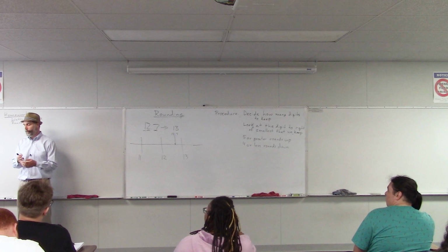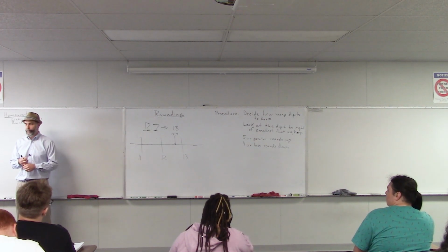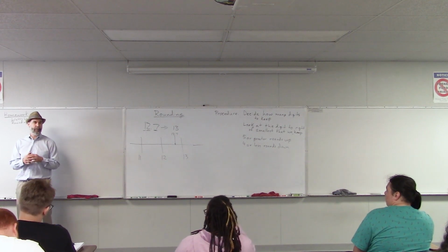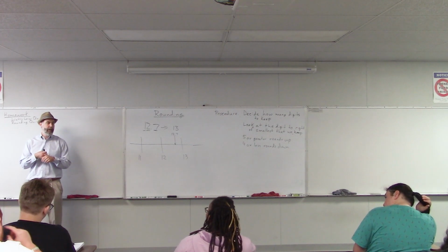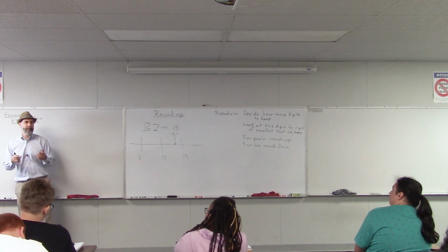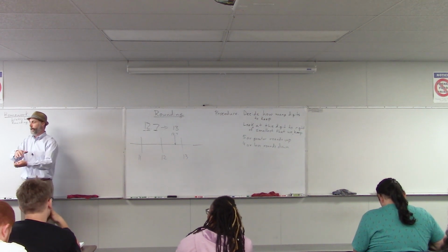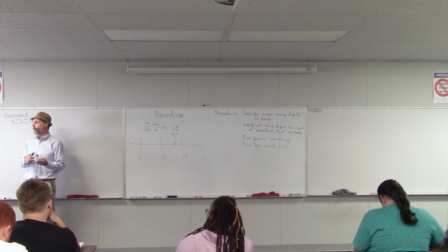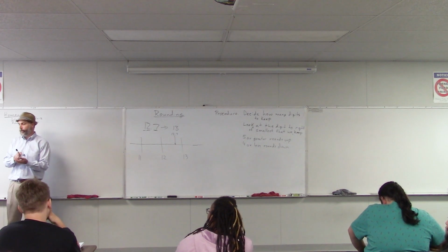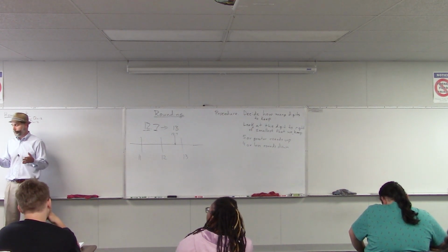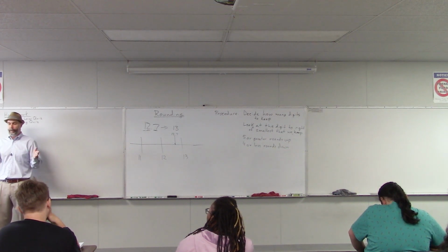With certain types of measurements, you want to be very, very precise. Like, I took a trip up to Agilent, where they have a repair facility up in Roseville, and they do calibrations up there. They have machines that are used to calibrate the oscilloscopes and the digital multimeters that we use in our labs. To calibrate something, the standard you're using has to be about 10 times more precise than the thing you're trying to calibrate. They're calibrating some really sophisticated machines, so they have standards precise out to 10, 15, 20 digits of measurement. If you're using something like that, you need to keep all of that data, okay? So all of that would be relevant.